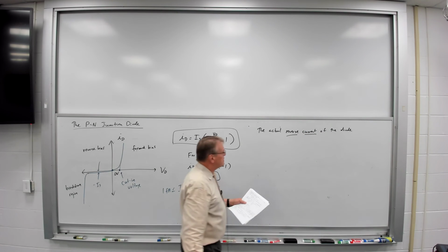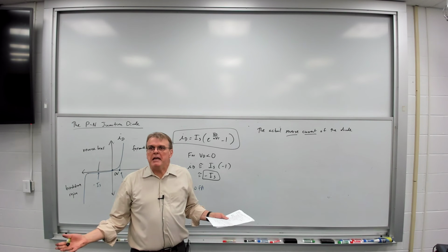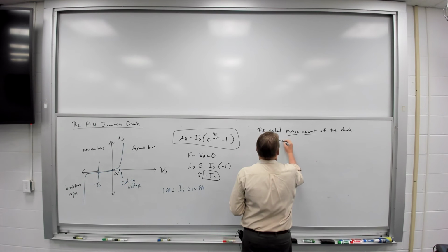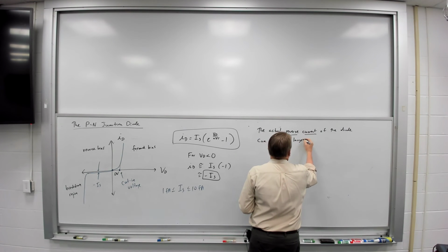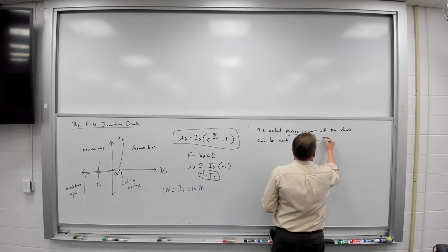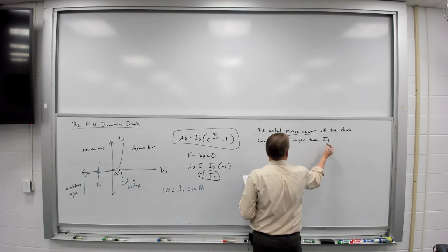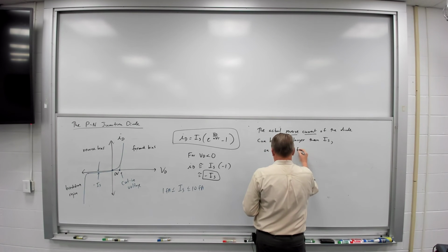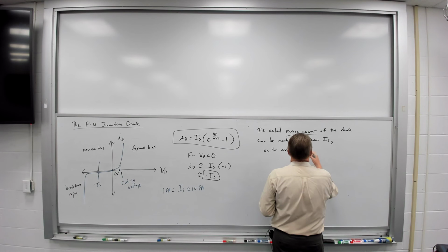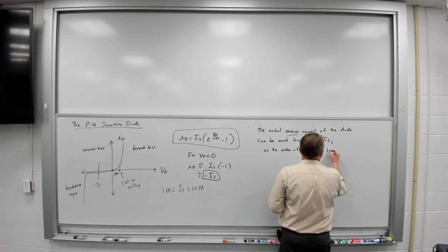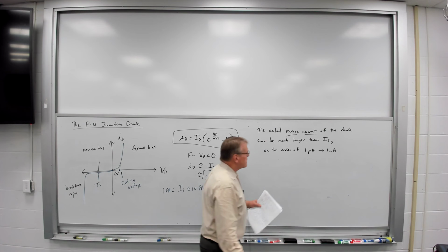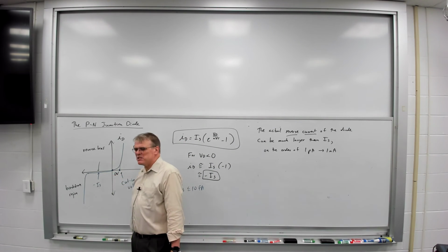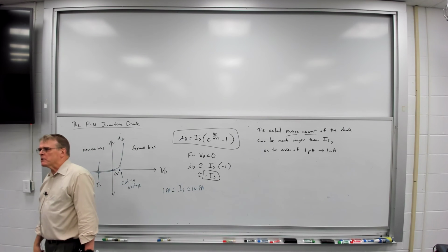It can typically be on the order of picoamperes to nanoamps. So you'll see that the reverse current is generally not femtoamperes. If you actually measure it, you may find instead it's picoamps, much larger than you would expect.